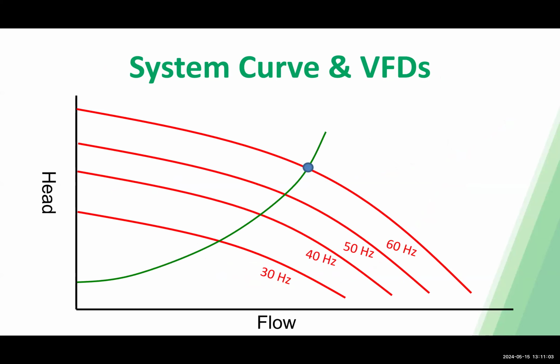That's the whole point of using a VFD. But with a VFD, you also run into issues where you're dropping that velocity through that pipe network as well. So for this specific one, if you hadn't mapped out that system head curve and you wanted to operate at 30 hertz as well as 60 hertz, you'll notice that you're not hitting that 2 feet per second scouring velocity for that network, which will mean that you're going to run into clogging issues for that system.